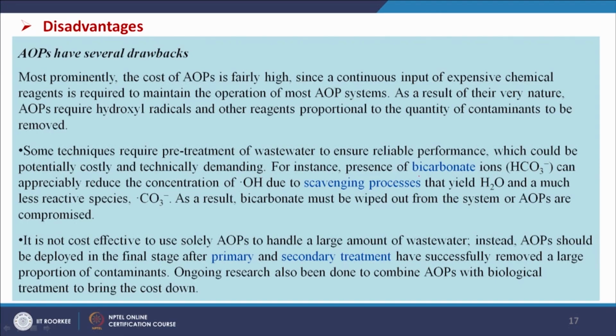For instance, the presence of bicarbonate ion can appreciably reduce the concentration of OH dot due to scavenging processes that yield H2O and a much less reactive species, the carbonate radical. As a result, bicarbonate must be removed from the system or AOPs are compromised. So, in the presence of bicarbonate, this system may not be effective.